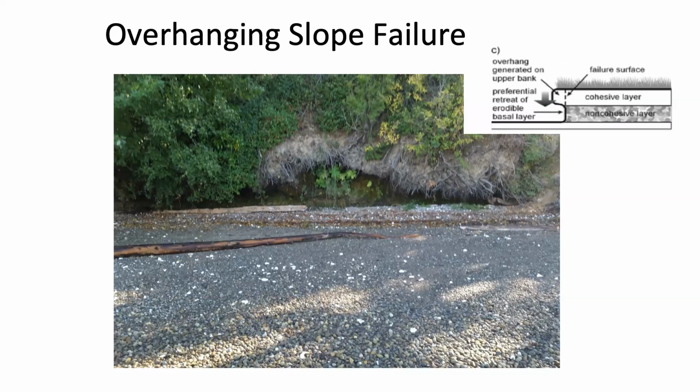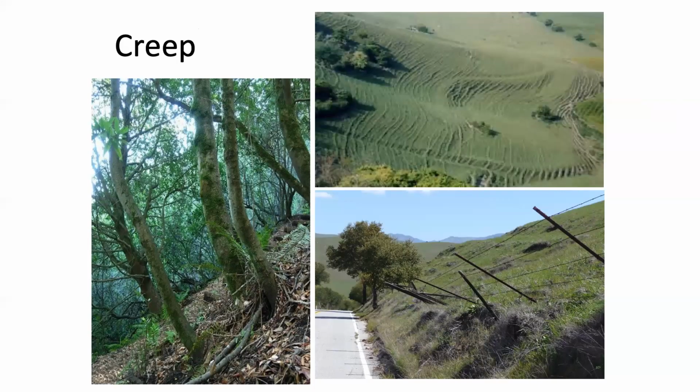Over time or with the input of water into that upper layer, that overhanging bank is going to fall into the shoreline and the process can start back over with toe erosion. Now I mentioned that could be a creeping slope. It's hard to identify because it's hard to see on really close photos, and so we look to larger scale photos. But here's the best I could do. It's really hard to show the effects without really big scale photography.